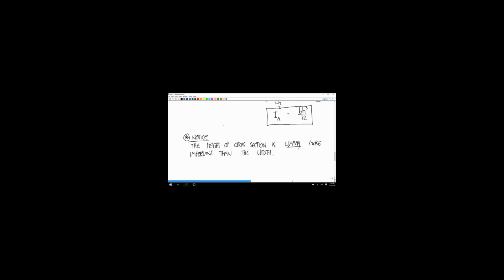How many people here have ever taken intro to engineering? Anyone? Did you do the bridge crushing thing? Okay, so you probably either sort of intuitively understood this about resistance to bending, or else you sort of figured it out as you went. You didn't get rewarded much for using your material to make the thing wide. You only had to make it wide enough that you didn't get some kind of weird twisting and then it would break the other way. What you're really rewarded for is making it tall, getting the material separated really far from the centroid vertically.